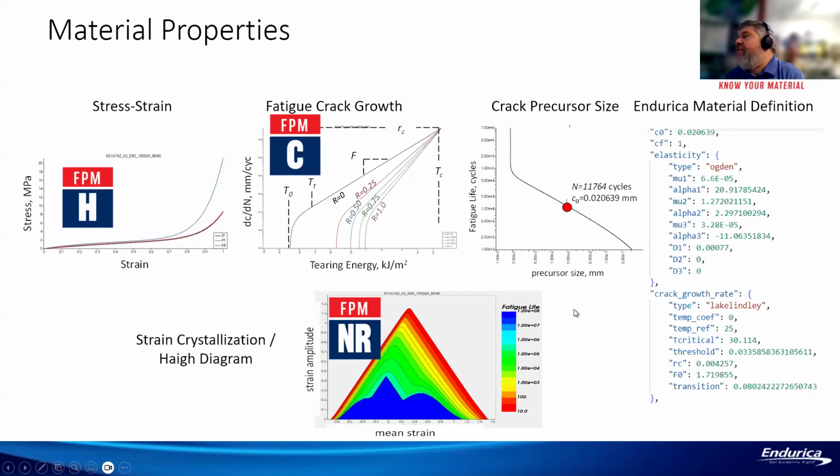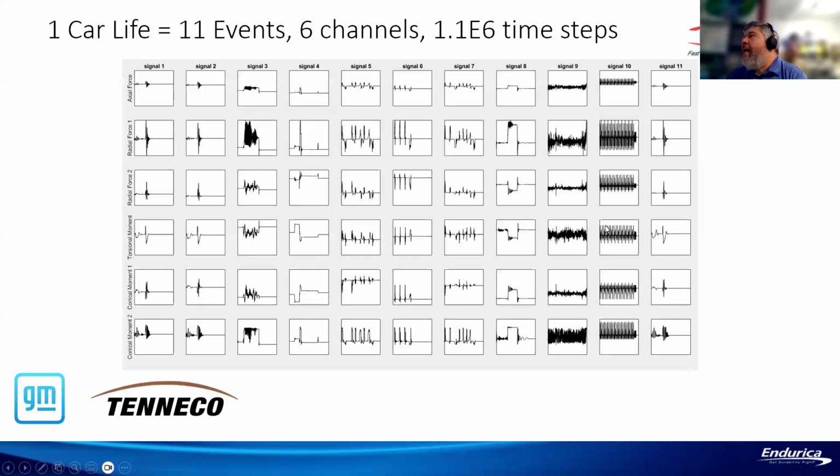So that's what we've done for this. When you're concerned about high accuracy, it's important to measure your own rubber. If accuracy is less important, the software does have a materials database, and you can make some estimates just based on database numbers. But for the best accuracy, you really want to measure your own materials.